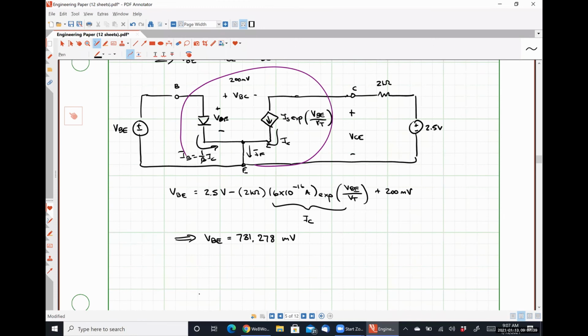When we're in saturation, if you were to look at the transistor as a switch, that's when the switch short circuits, and cutoff mode is when the switch open circuits. So for any type of amplifier circuit, we need to make sure that we're operating in the forward active region where we can get some small signal gain.